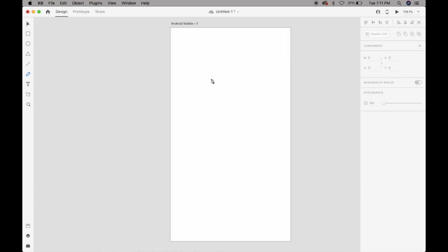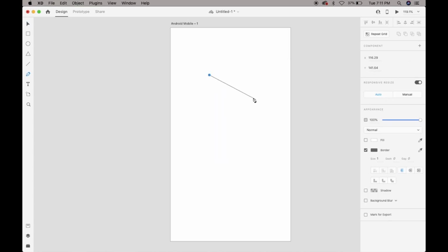Or you clicked one side, then you click the other side. You have to press and drag, then your nodes will be activated from both sides. We cannot delete this node from Alt like Photoshop. So we can change its position by pressing Alt. You can also use the pen tool in this way. Along the mobile app and website, we can also create icons and illustrations.